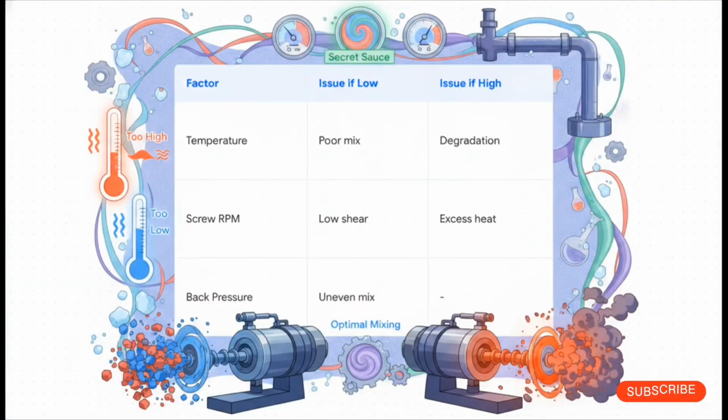Beyond the raw materials, we have the processing factors. These are the dials we actually control on the floor. Finding the perfect operational balance is a must. If your temperature is too low, your dispersion is garbage, but if you push it too high, you literally degrade the pigment. As for screw RPM, run it too low and you don't get enough shear force to break those agglomerates. Run it too high and yeah, you get better mixing, but you generate excessive damaging heat.